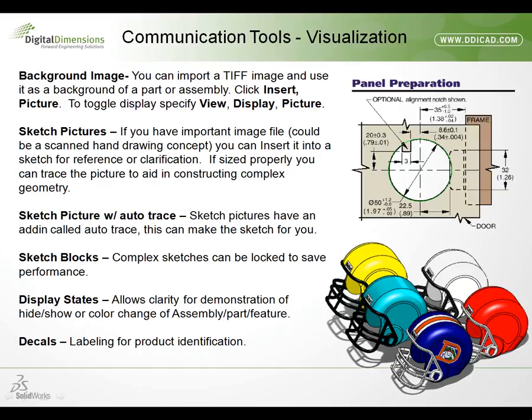This also works really well in reverse engineering older parts that you've manufactured that perhaps you don't have drawings for anymore, or the drawings that you do have are hand drawings that were scanned into the computer. You could, again, take these raster images and bring them into a SOLIDWORKS sketch, scale it, and then trace over the top of it. It could also be used to make quick representations of off-the-shelf parts that you plan on purchasing but cannot get a model for, nor can you get accurate size dimensions for.